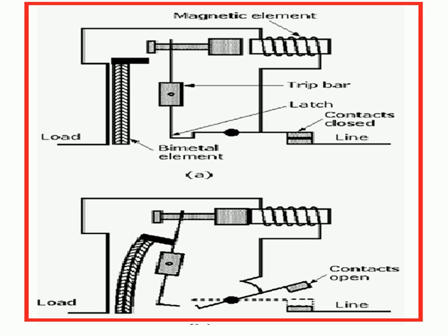So during the short circuit condition or fault condition, this operation is mainly carried out by the magnetic coil. Hence both are designed, the bimetal strip action as well as the magnetic field developed. Both happen in circuit breakers. You understand, please, sir?